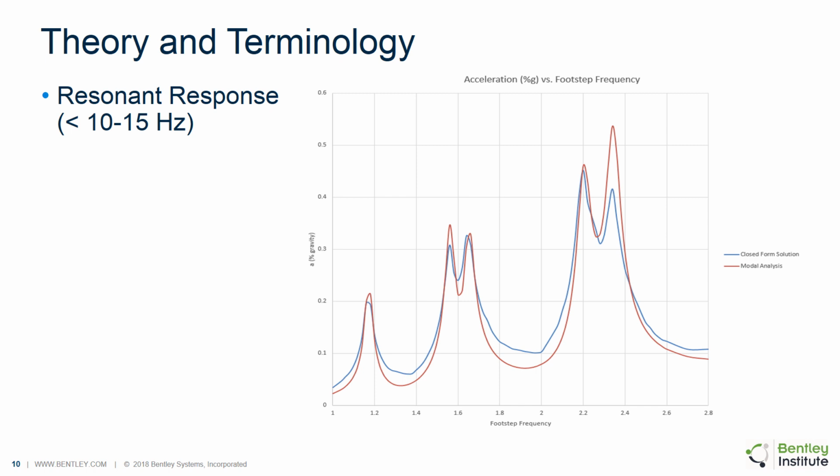If we start by looking at the one at the far left, which is around 1.2 hertz, most concrete structures are not going to have a natural frequency that low. So it's likely that this response was caused by resonance with one of the harmonics. In fact, the fourth harmonic of that frequency is 4.8 hertz, which might align with near the lowest frequency natural frequency of the floor. And so in that case, if you recall, when we're applying dynamic load factors, the higher the harmonic that we're calculating, the lower the dynamic load factor.